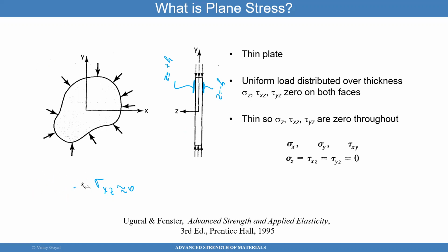Okay, let's look at that carefully so we can understand what is going on there. So tractions equals stress times the normal. But I want to examine that face here. That normal is 0, 0, 1. And on that surface, I have no tractions, nothing. So that's tractions equals 0, 0, 0.